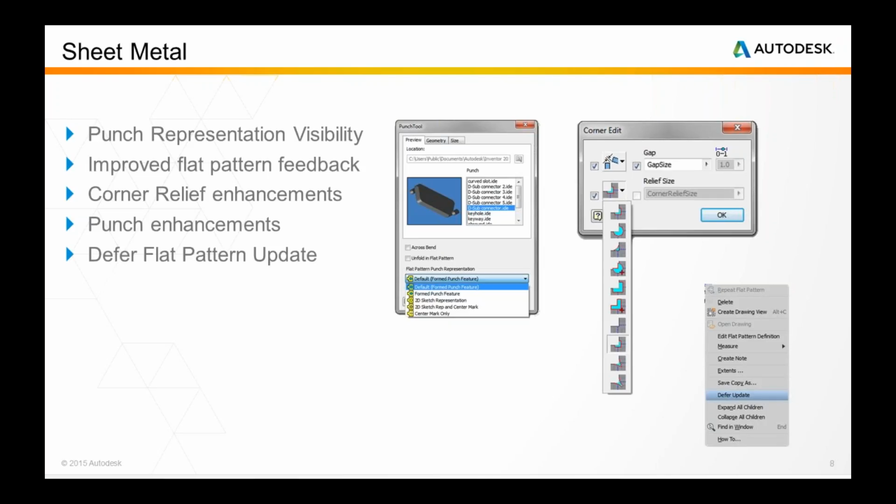They've also added some enhancements on the flat patterns, as far as now you can defer the update of that. If you're adding some holes, adding some cuts, putting some bends across, stuff like that, you can defer the update in the flat pattern, and it's an efficiency, time saver type of thing. Obviously, eventually you probably want to update the flat pattern, but you can hold off on that until you're all done with the parts or the features you're putting on your form view.